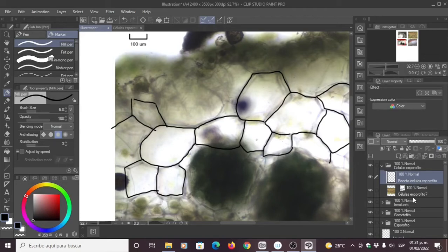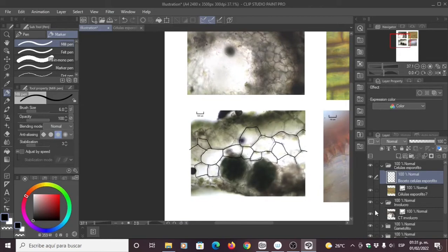That's why the draft and also the individual layer is important, because that way I just change the draft to a different layer. If I had all the drafts on a single layer, then I would have to move with the lasso tool, and that is time consuming and not useful. So that way I made a mistake, but I can correct it very fast.